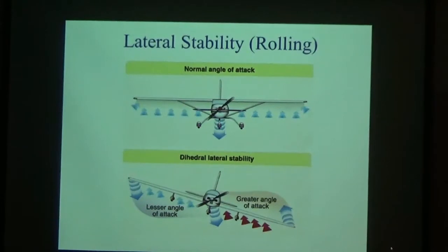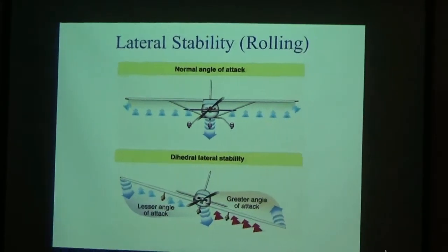The angle of attack stays high if one wing is lowered and will attempt to lift back to its stable position. If the other wing is lowered in the process, it will then be lowered and raise up until the oscillations subside. In addition to a dihedral design, aircraft may also have wings that are swept back. This design allows the lower wing's leading edge to hit perpendicular to the relative wind. This causes greater lifting effect, and the wing restores to its original position.